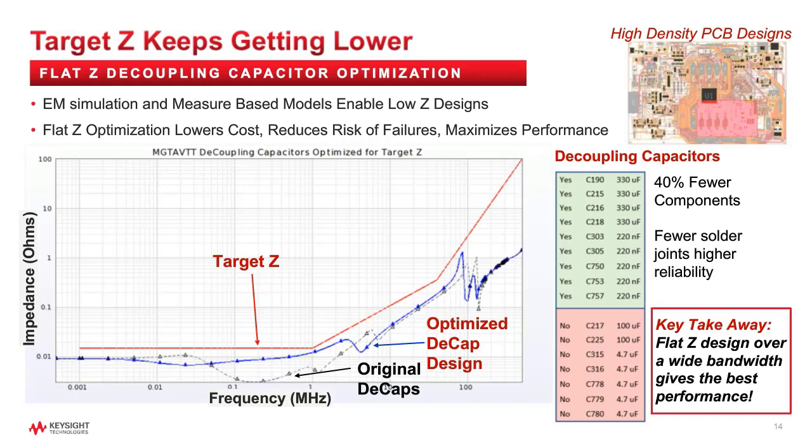The first breakpoint, around 1 megahertz, shows the frequency at which the internal package die capacitance is starting to provide the power to the load. The third breakpoint shows that the spectral content of the load is rapidly diminishing with frequency, and higher PDN impedances are allowed as the di/dt at those frequencies goes to 0.